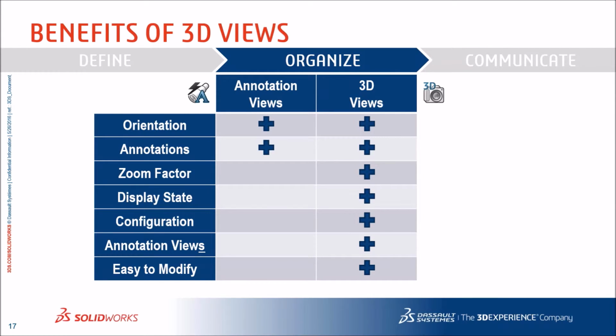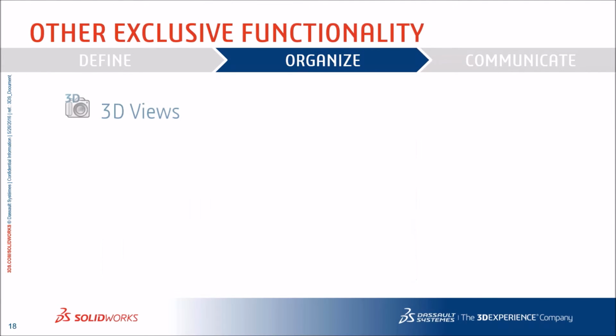We do have annotation views in the standard version of SOLIDWORKS, but what MBD really enables is the 3D views, which control so many more parameters that are critical for, again, producing this in a format that's easily viewed and consumed by someone maybe out on a greasy shop floor with a touchscreen tablet or a computer monitor without having to click a bunch of buttons and reorganize things. They're just clicking on the views that they need and it's already displayed appropriately.